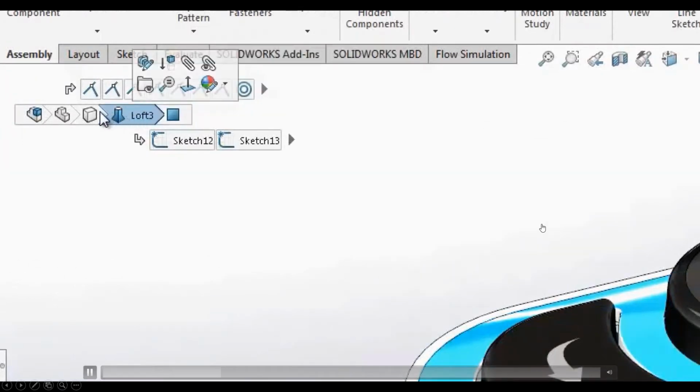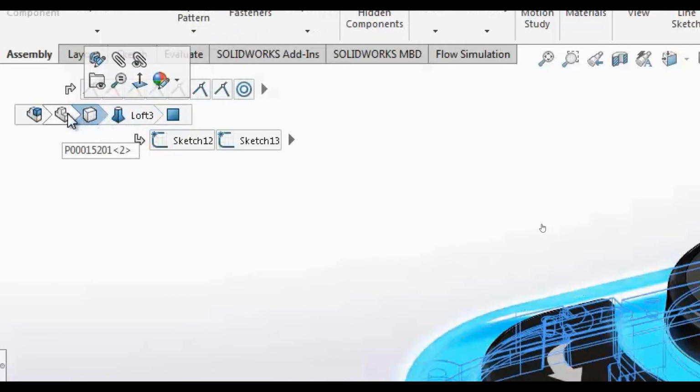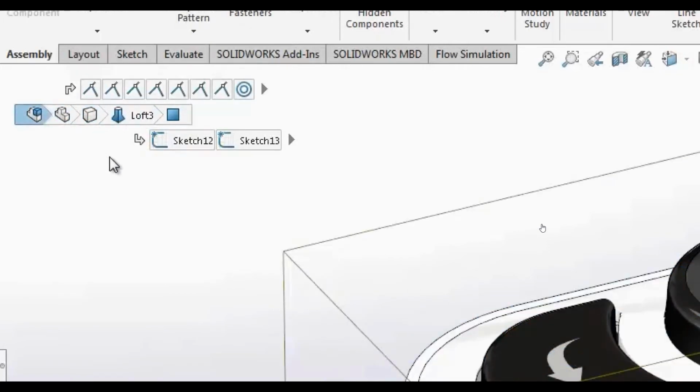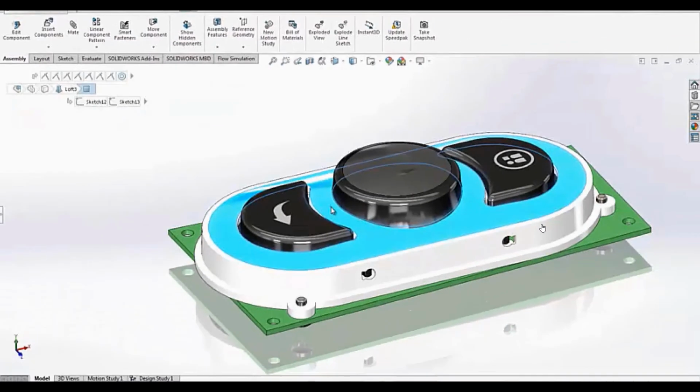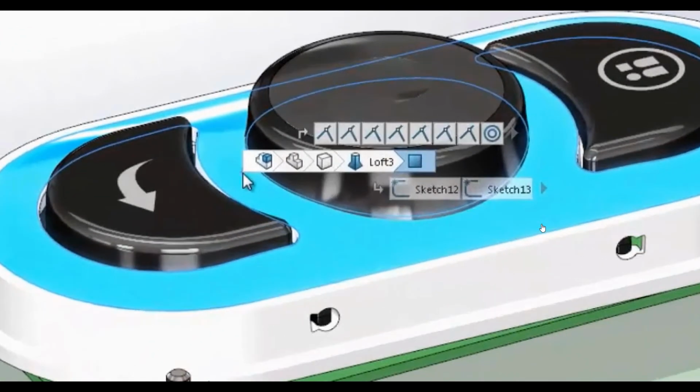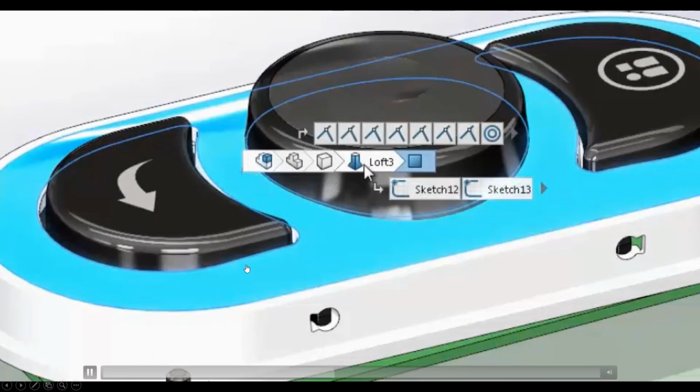So, right, if I've got some of this different geometry, you can quickly get to your various mates if you're in there. And the key thing that just happened there was when you hit your D key, it's going to bring those breadcrumbs directly to your cursor. So you don't have to actually go up into the corner. Hitting the D key brings them right there. You can start clicking on stuff as you see fit.